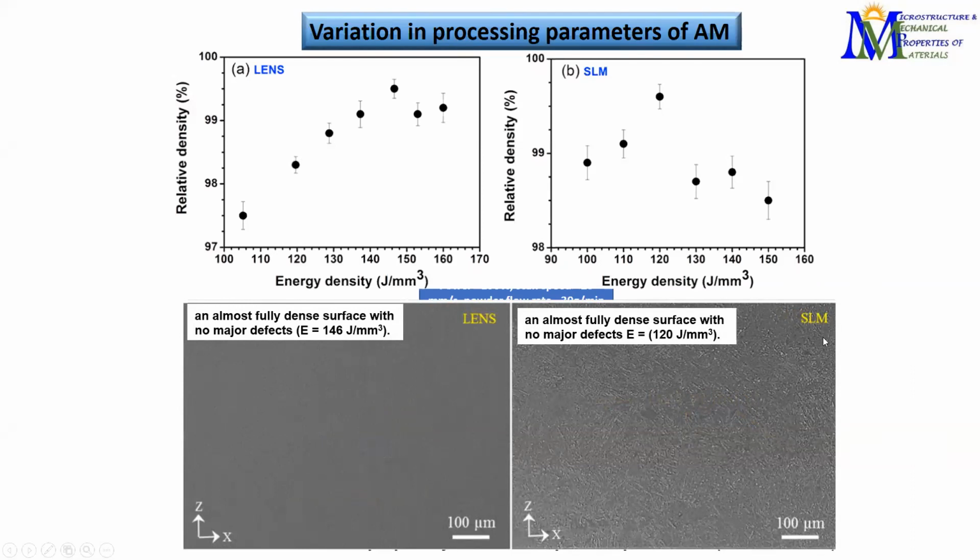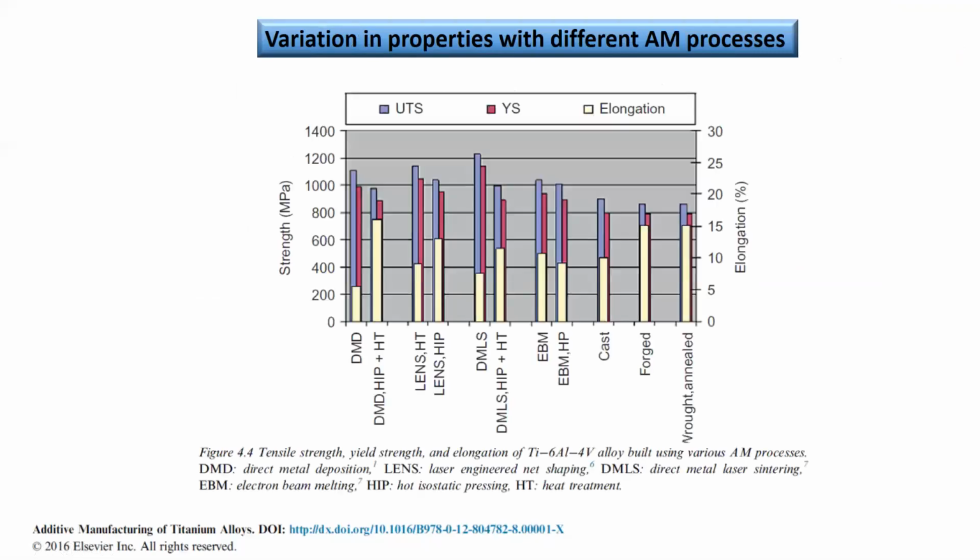And we can see here that SLM is beneficial in that regard. We can achieve the same amount of density, and that too with the formation of martensitic structure that will lead to higher hardness and ultimate tensile strength, even by using low energy density. And low energy density, the industry people will read as lower cost of production, lower time of production, so that will be much more efficient. So we need to know all this information before we can use this for any practical purpose.